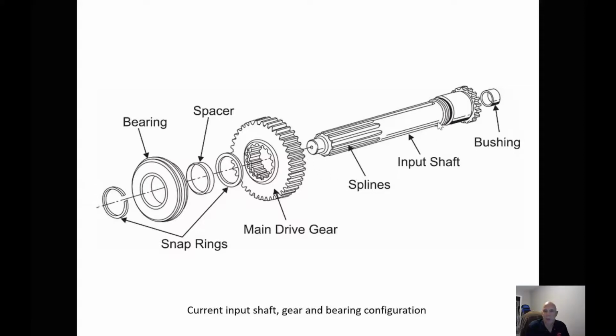Now, when we're doing the inspection on a transmission, let's just say, for instance, we're pulling the transmission to replace the clutch. We want to inspect the input shaft. We're going to talk about this later when we're doing clutches, but we want to make sure that where the pilot bearing sits isn't worn, and where the splines are, that they aren't worn, because if they are, well, we've got the transmission out. It's quick and easy to replace this input shaft, and we should do it. Otherwise, we're going to have premature wear on the new clutch plates.